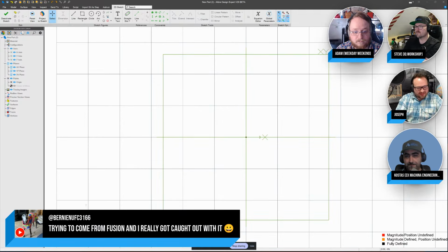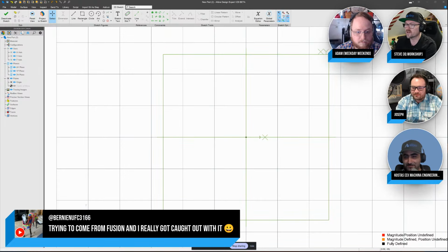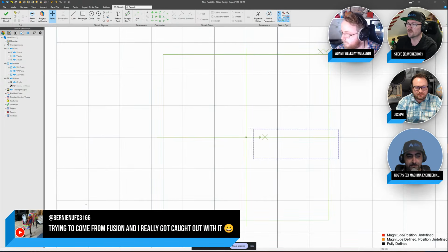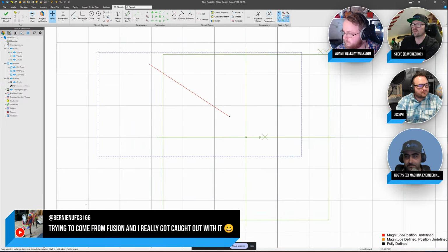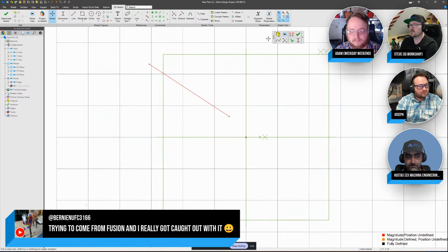Yeah. But still, I like that suggestion. I'm changing the subject again, to that click and drag rectangle. So I want to look into that and see what we can do. Sounds really nice, actually. Yeah. There's a few other selection options that I'm going to potentially expose my lack of knowledge here, but clicking and dragging in one direction versus another direction when you're selecting things can often yield a different result. So if you click and drag left, you can select a single line that's within the selection box. But if you click and drag right, it selects anything touching the selection box.